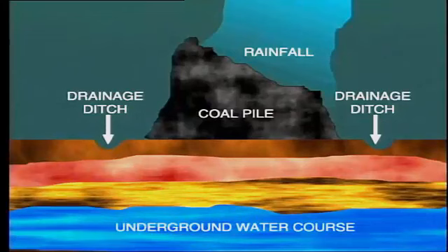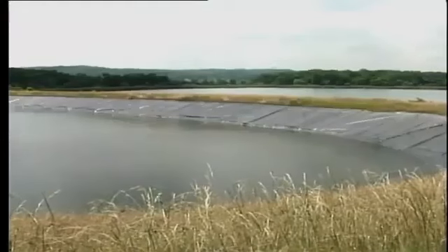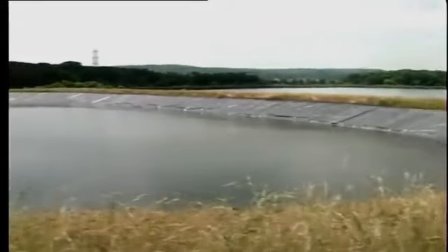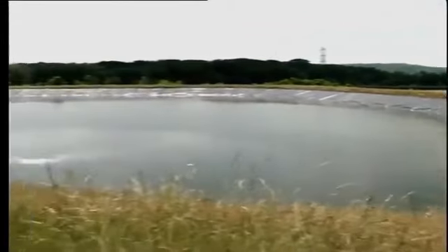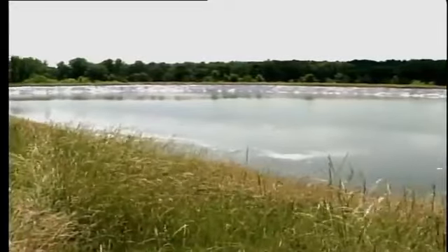This water, taking with it contaminants, some of which may be hazardous, percolates down through the earth. There it may find its way into the natural groundwater, which is often used for drinking by animals and people. Nowadays, it is necessary to install an impervious liner, usually of heavy plastic, below any of these areas, including the ash pond.